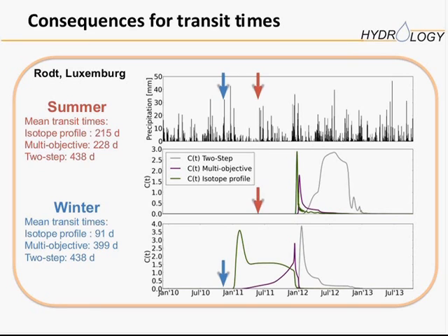In trying to sample the moisture or the vapor from the soil moisture, you talked a little bit about how you were using dilution with the dry nitrogen gas instead of trying to heat the lines to prevent condensation. I'm wondering if that's feasible at lower concentrations of water vapor in the analyte gas. In other words, if we're trying to measure, let's say, atmospheric vapor, at which the humidity is presumably much lower than where you're getting it from the soil equilibration.